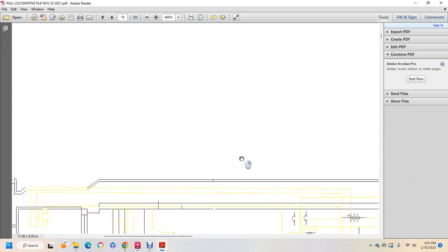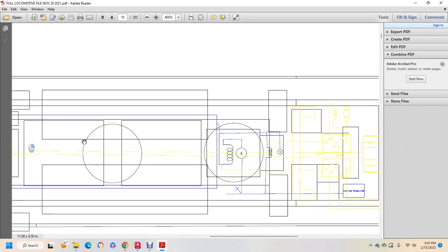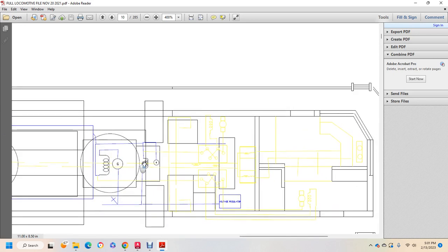If you went to look at the allocation, you can barely see this in yellow, but you have a starting crank canister, voltage regulator, main generator, and it shows the strainer over here, and how it goes into the second path, and the dual engine control panel with ammeters and circuit. That's the DC circuit.